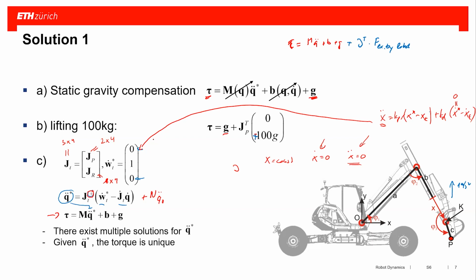The same if you say we have joint limits or something, then we also have to define the limits that are on position or on velocity level. We have to move that through a feedback law, potential fields or something, up to the acceleration level in order to integrate this the way we have it here.